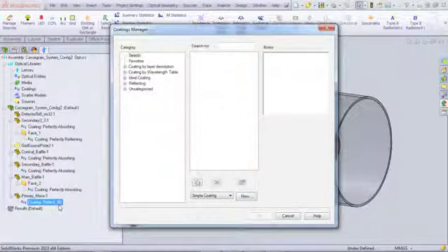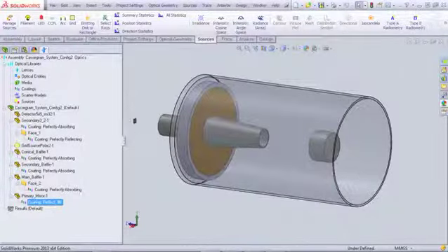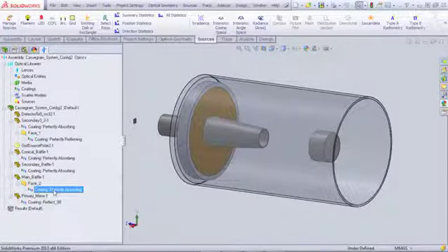Changes and edits to the optical properties are made accordingly. If you edit a property that's been applied to this configuration, any changes that you make are only in that configuration. If you edit a property that's been applied to all configurations, then that change will be propagated to all the configurations. When you delete an optical property, it always deletes from the current configuration.